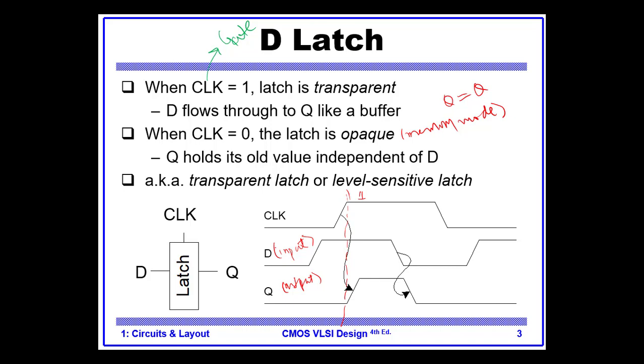Whatever is at the input, it comes here. Of course, after a delay. The delay is required for passing an input towards the output. Because there are transistors inside, those transistors take a certain amount of time to propagate the signal. So after that propagation time, whatever is at the input comes out at the output.